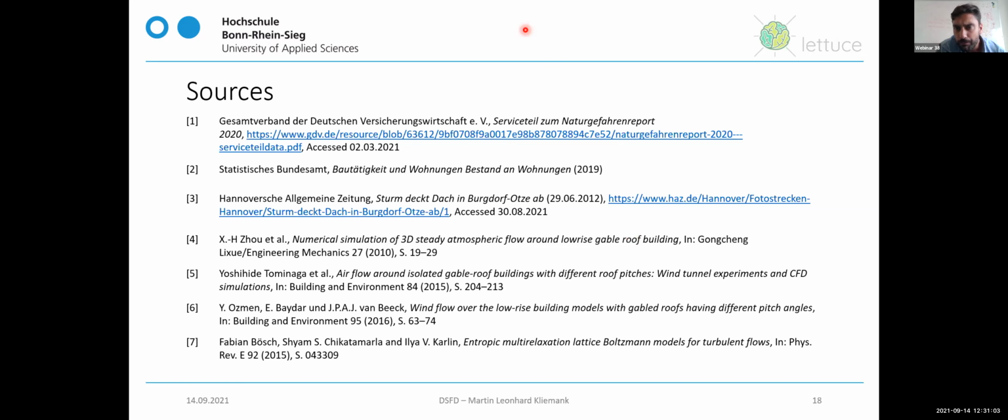Could you comment on the use of the D3Q27 lattice as compared to the D3Q19 counterpart for a better representation of turbulence? This does not seem to be in agreement with what is done in the industry for high Reynolds number flow simulation. This is Christoph, who is asking.